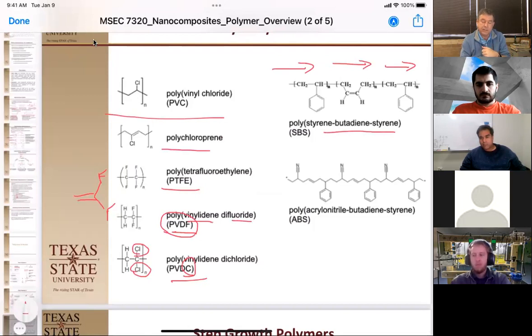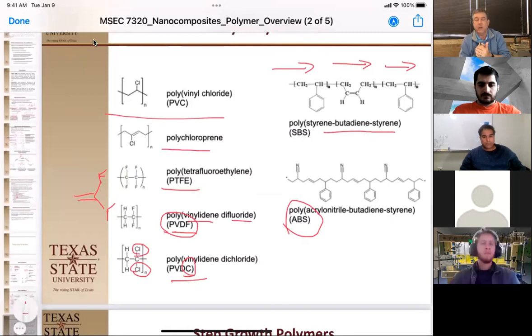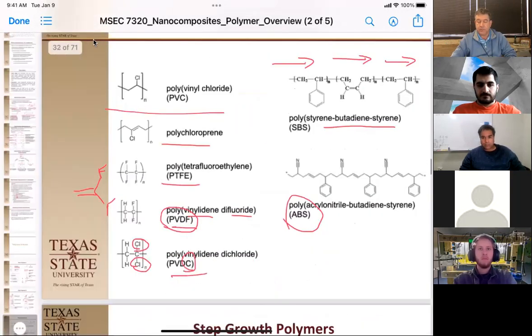And then this is a workhorse of the handheld devices industry, ABS plastic. It's tough, it's easily molded, it's fairly impervious to a lot of solvents. It's used a lot. So that's ABS plastic, is acrylonitrile butadiene styrene. All right, so those were all vinyl-based polymer systems.